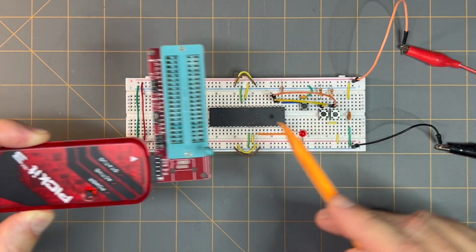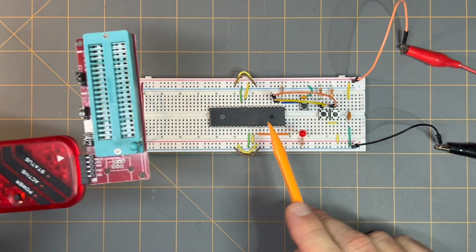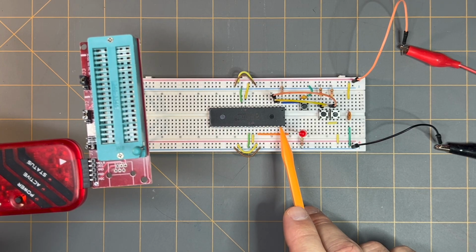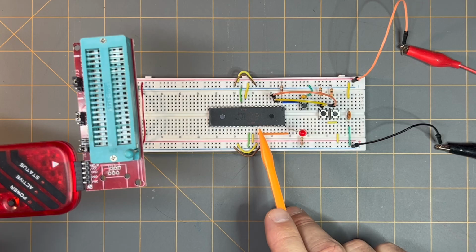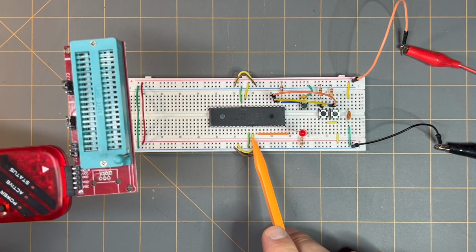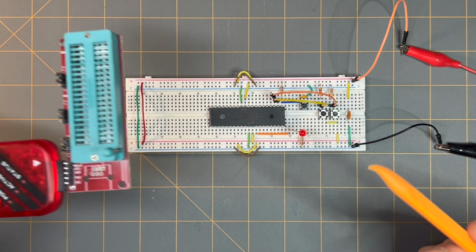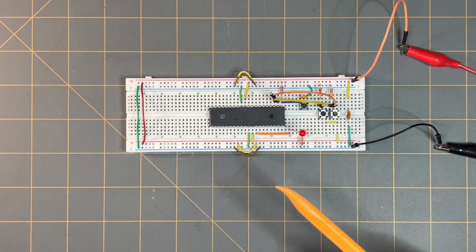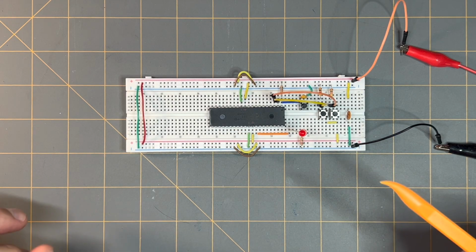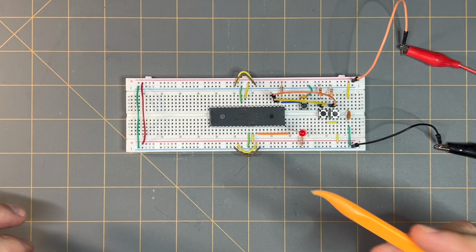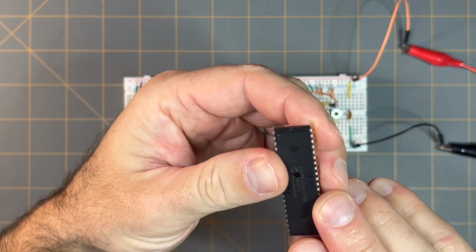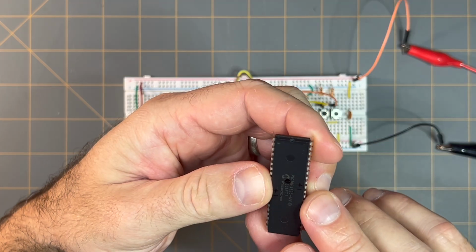Every time we take it out and need to place it in, it becomes quite tedious to count the pins and to figure out the alignment of the pins back on our breadboard to the connections that each pin needs to be on. So to make things a bit easier, before we get to prototyping our circuit on a breadboard, I find it extremely helpful to make some marks directly on the PIC's body before I start making any connections to the pins themselves.